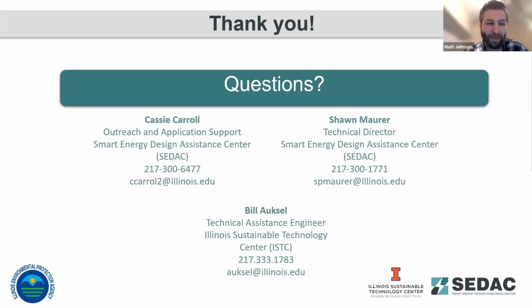I could jump in. Wastewater is primarily the applications that I work with. So sludge pumps can definitely benefit from VFD use. Oftentimes you are simply pumping that around the treatment plant, so there's not a lot of elevation change. So a lot of the head that you see is dynamic head. As you decrease the flow, you're decreasing the velocity and then the head. So there's a lot of specific energy saved.